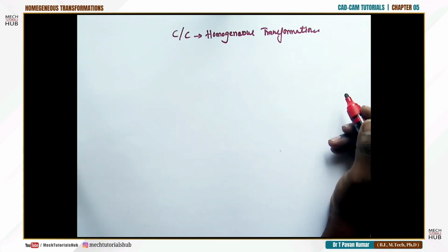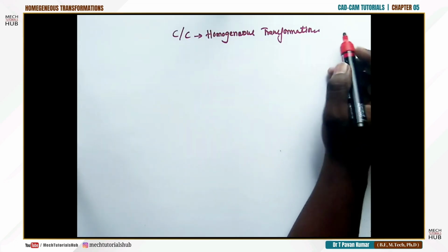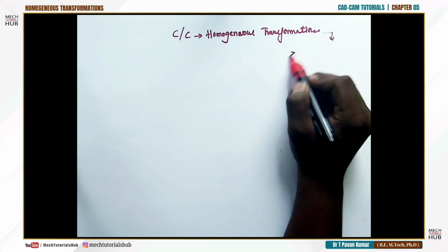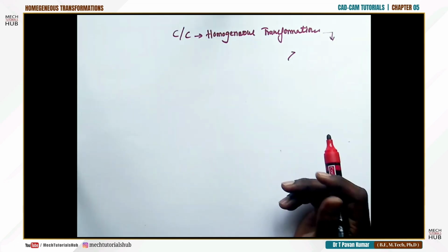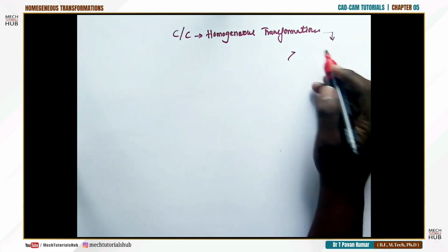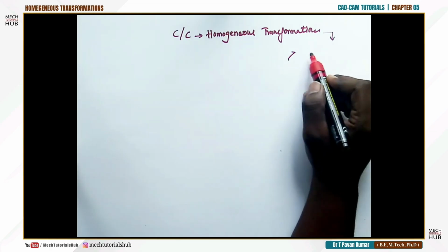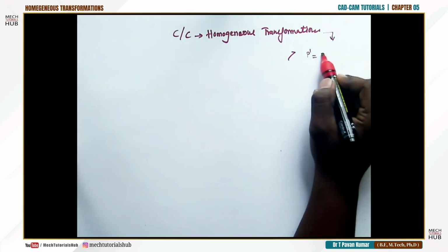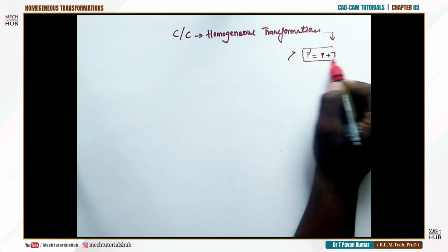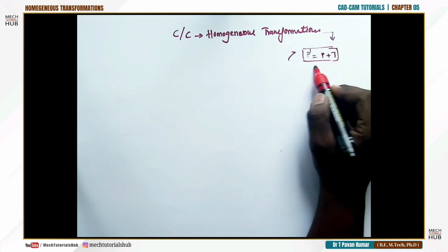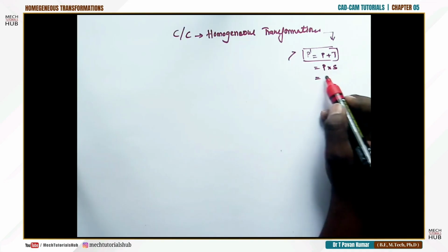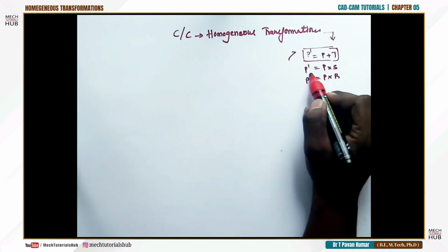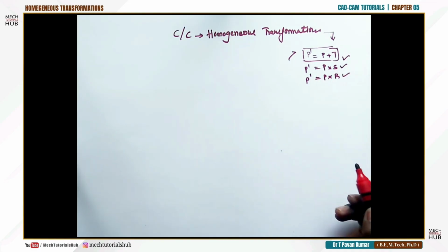The reason behind this particular transformation is this will help you if you talk about the advantages of homogeneous transformations. First, translation can be captured in matrix multiplication format. Earlier we have seen the equation of translation is P prime equals P plus T. Whereas in case of scaling it is P multiplied by S, and in case of rotation P prime is P multiplied by R. These are all three we have seen, and we have solved three problems also.